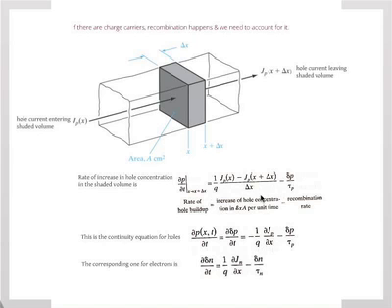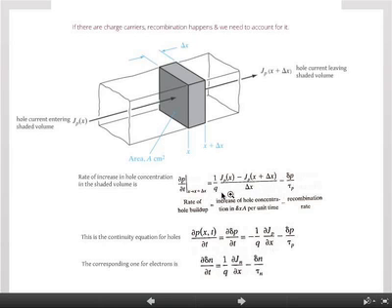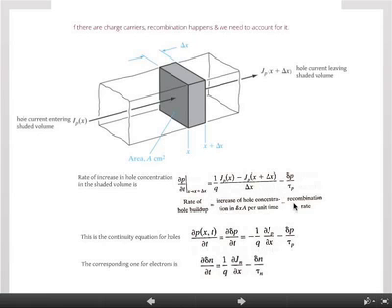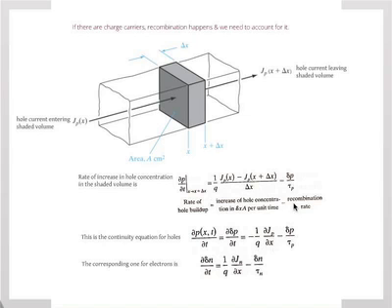So this is straightforward. 1 over q, because q is the charge carried per hole, minus what you lose by recombination. And that's the term we saw a couple of weeks ago and also very briefly last class. Basically, we have a recombination rate that is proportional to 1 over tau p, where tau p is the lifetime of the holes. This is the average time that the electron-hole pairs remain separate, the average time between recombination events. And we saw that before. It's a negative sign because it decreases the total concentration, because you're losing the holes. Okay, so that's a fairly simple equation.